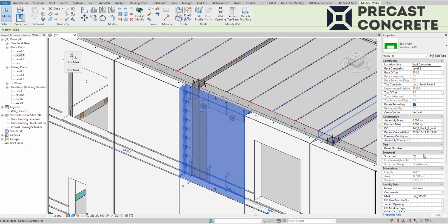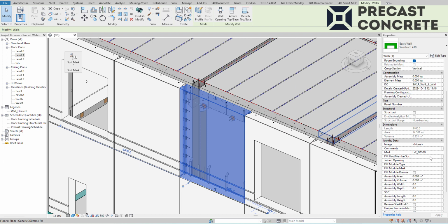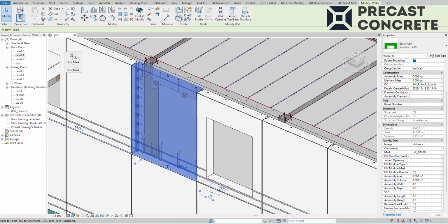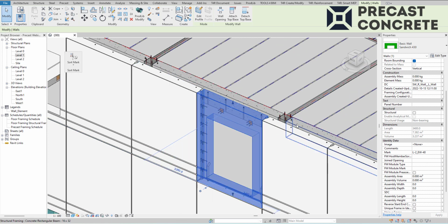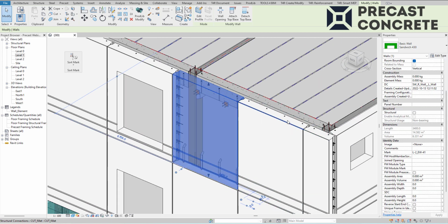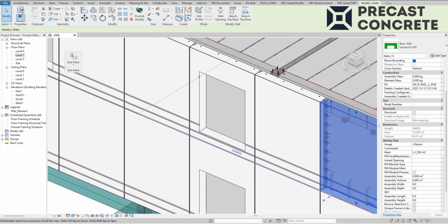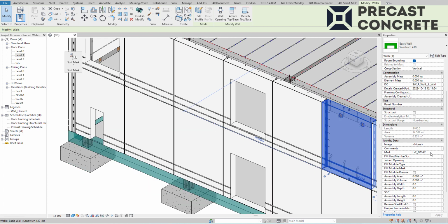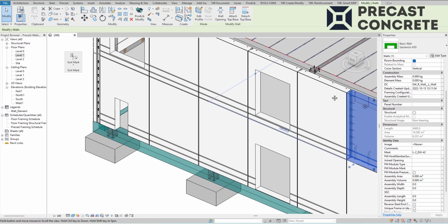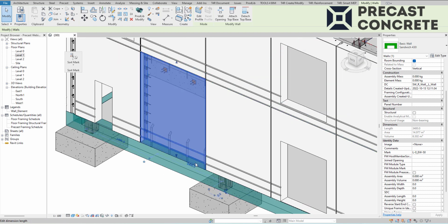And we can see what the mark value is in the mark parameter. So L2 stands for level 2, EW stands for exterior wall, 39 is this wall's number. And we have the same here, level and number. Also, exterior wall, and here. And this mark value can identify not only the level, or if it's exterior or interior. You can add different information into this mark parameter.